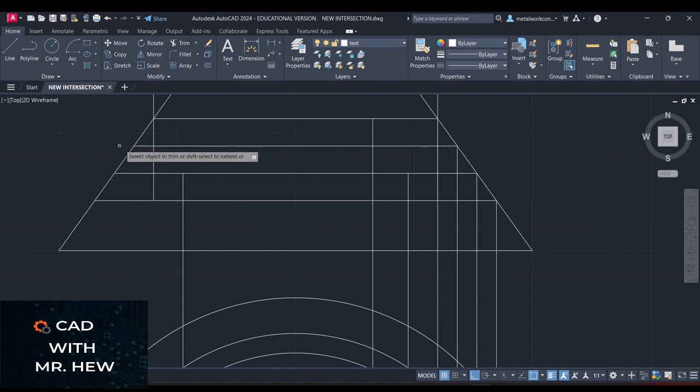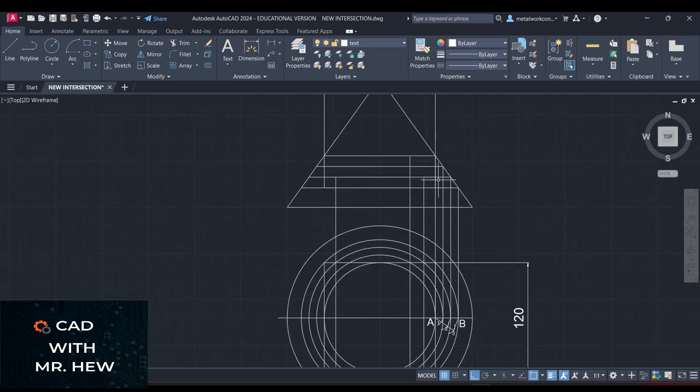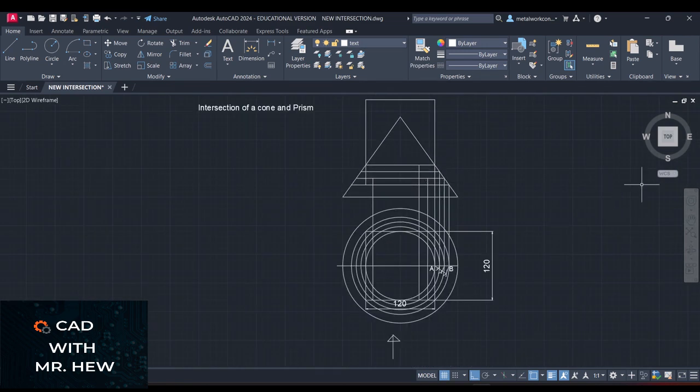As I said, if we were using the traditional instruments, which would comprise a T-square, two set squares, the 45-degree and the 30-60 set square, compass and pencils and French curve, you would let it stay, all right? But for AutoCAD, I want to keep it neat. All right, so that line coming up, where this line intersects this line, that will be the next point, right? We're going to do the same thing on the next side.